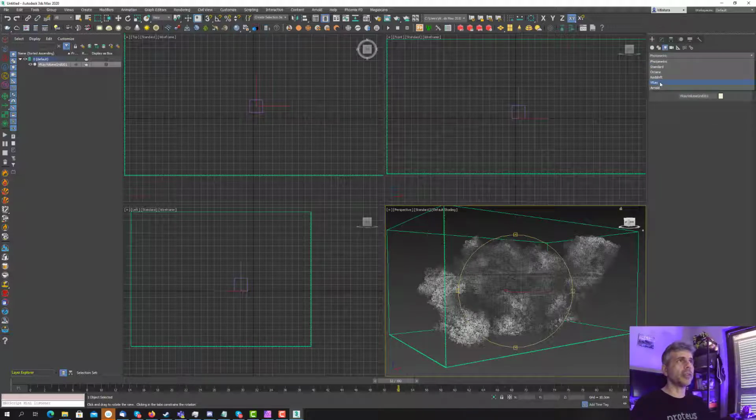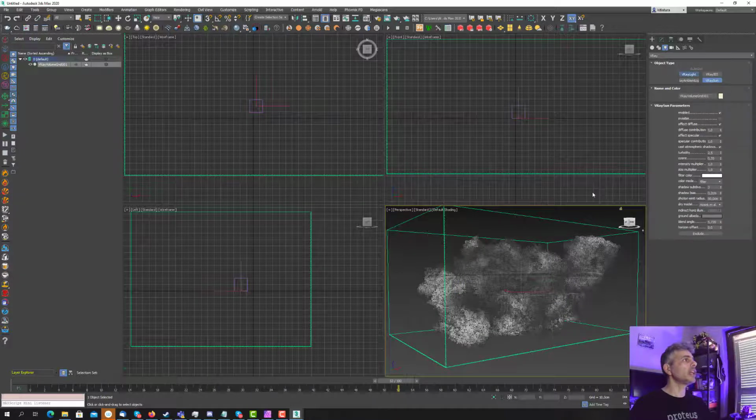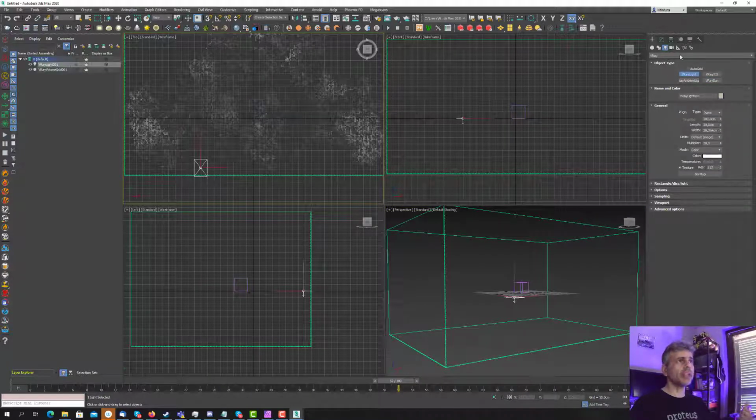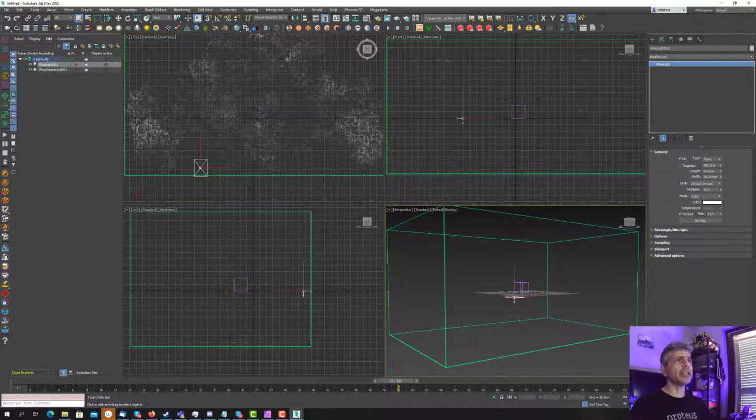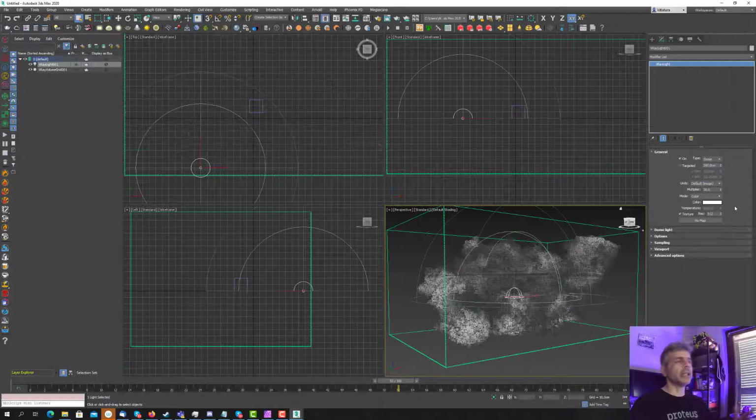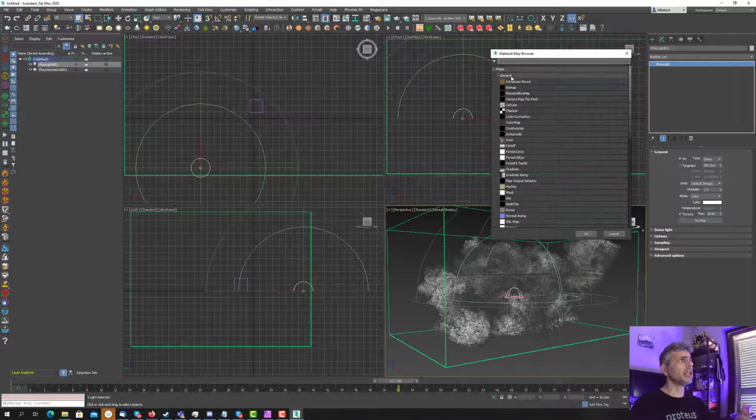Now we are going to set the lighting. We'll do something really simple. We'll have essentially a V-Ray sun, that's a direct lighting. But before that, we are going to create a V-Ray light, the dome light. We have to take care about the multiplier. We are not using the color management, so we set the multiplier to 1 and set everything manually.